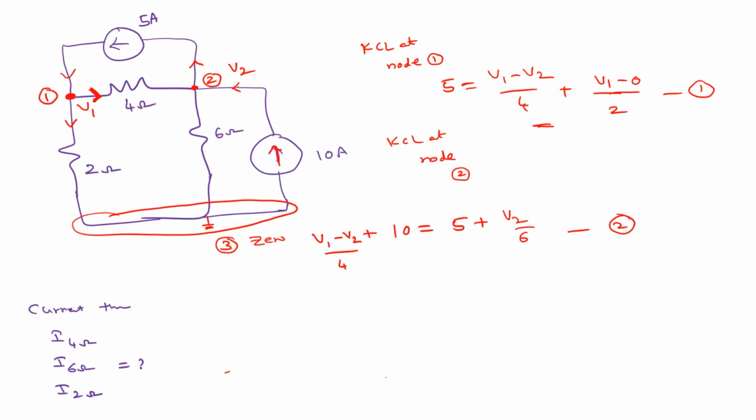Right. Now this current source direction is already given. This upward arrow means this is incoming, and this 5 is the outgoing, right? Now if you come to this 4 ohm, you already labeled this current. Either you use the same one, or you have your own. Normally we assume that the current is outgoing, so here also you can use outgoing. But if you already assumed this current, why assume again? If you assume it as outgoing it may sometimes be contradictory, so for simplicity I have chosen this same direction.